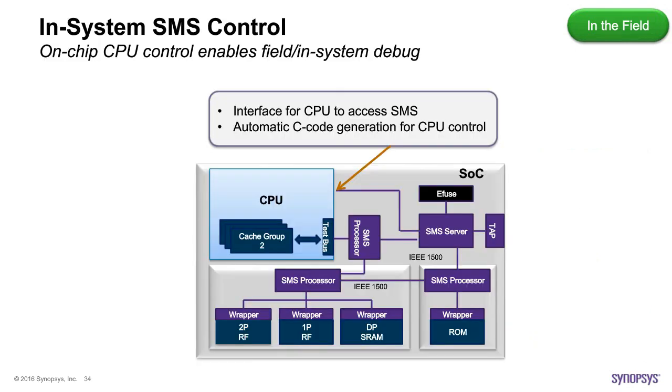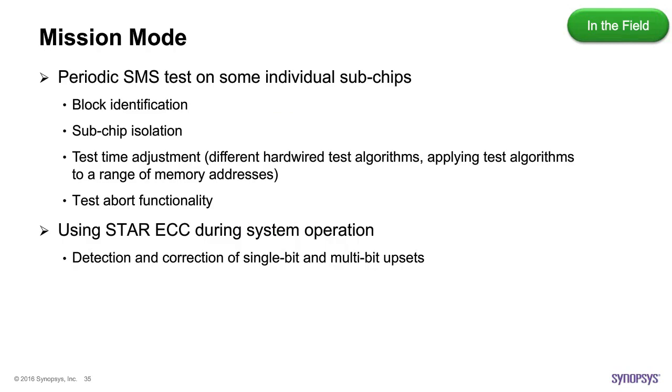Therefore, what we need to do is have the initialization processor that is sitting in the chip, that is starting the whole test and repair mode upon power up, take control of the server and be able to supply the necessary signals to run it in an autonomous way, in a previously prepared, scheduled way, every time the power on happens in the chip.